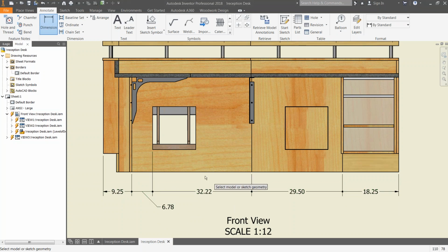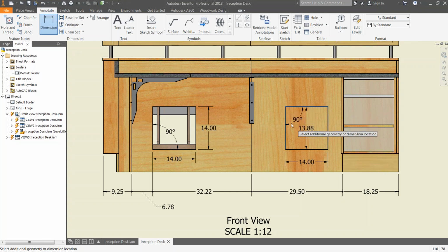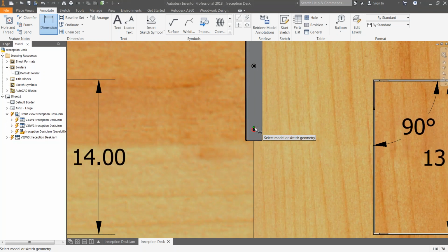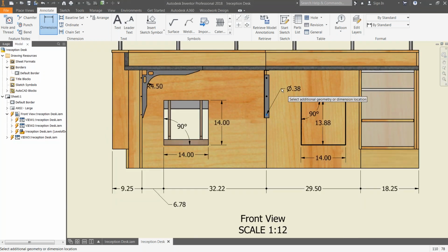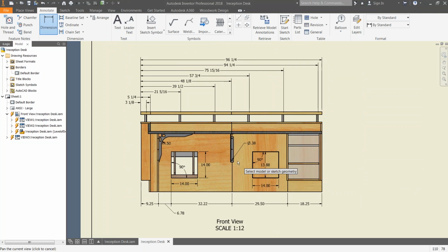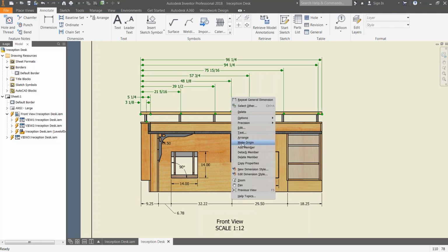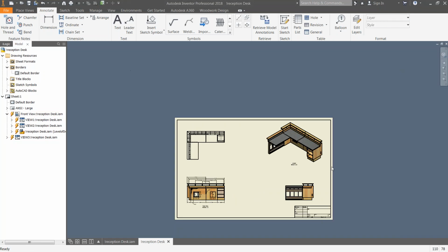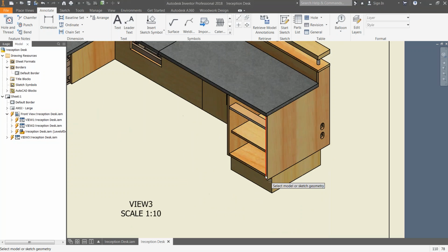Taking it further, we can start dimensioning individual items. I'm just touching items, just touch. If I touch two lines, 1 and 2, it's automatically an angle, so it's not a separate dimension tool. If we touch a radius, it's automatically a radius. If we touch a diameter, it's automatically a diameter. So again, the usage of these tools are quite good. Again, if we want to say the center is the origin, let's make that the origin instead. Let's go further. We do have the ability to dimension isometrics.